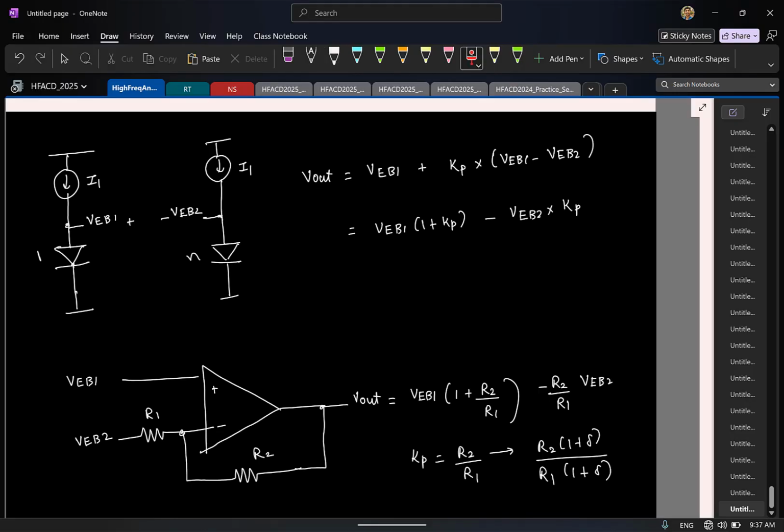It again boils down to the fact that on chip you can have a small random mismatch, provided you size elements to be large enough, and the ratio will be tightly controlled. There is going to be process variation, which means the exact values of R2 and R1 will not be known to you, but both of them will have the same value. Process variation is there that you can't do a lot about, but the random mismatch you can nicely control.